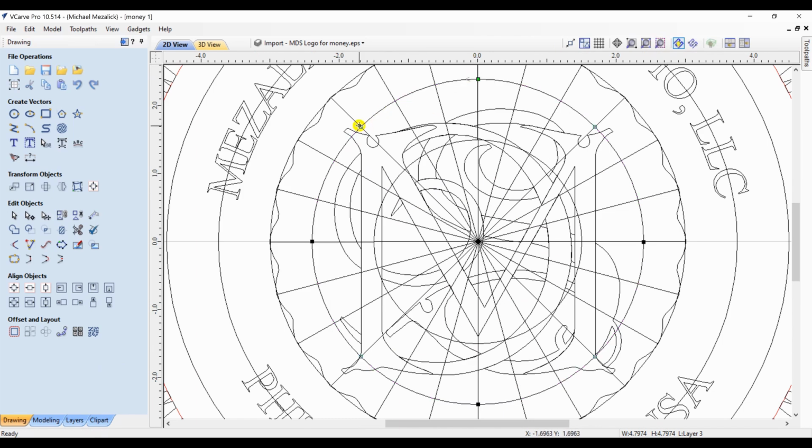That circle that I stretched out from the logo, I'm going to cut it apart, and we're going to use the text on a curve tool again. Hovering over a node and hitting the C key will cut it apart. And then hovering over the span and hitting the D key will delete that small section. Is it important to delete? Not necessarily, but it just helps me see where things are.